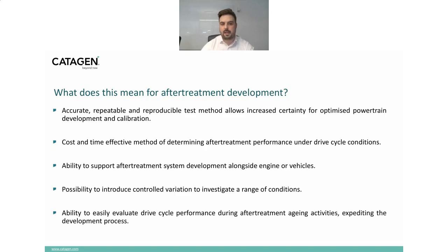Another benefit that we see with this is the ability to support after treatment system development much earlier in the design or development process, where we can develop the after treatment system alongside an engine or a vehicle. The case I've shown here is measured drive cycle data, but we can also handle simulated drive cycle data, which would allow us to evaluate the after treatment system on a driving cycle much earlier in the design process, where we don't rely on a donor vehicle or a donor engine to test on. That means we can get this really high quality, high value data much earlier in the process.